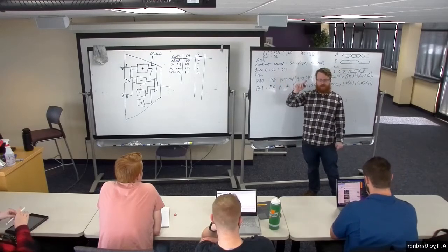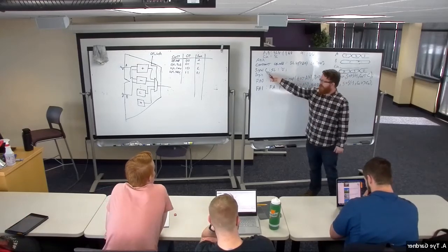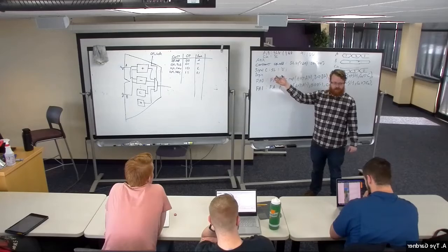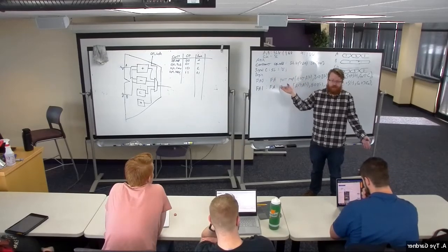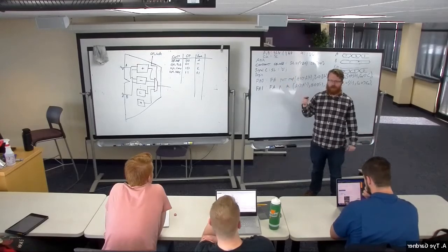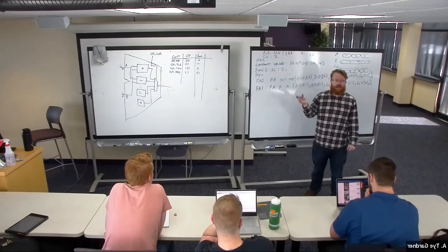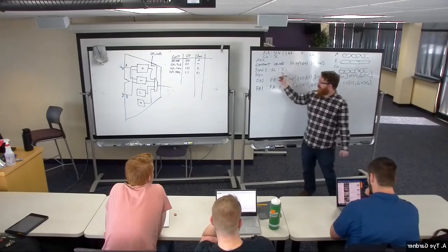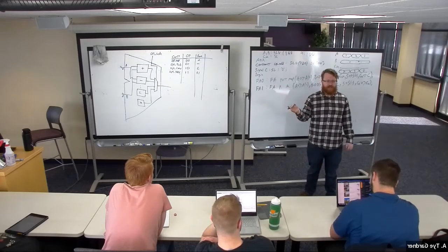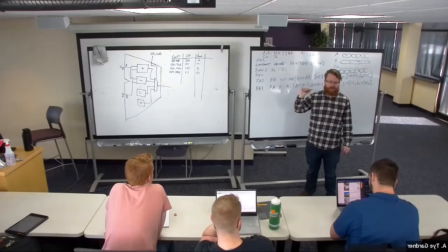Well, the issue is twofold. One, in your simulation, if signal C is not getting assigned to something, we would like it to be undefined because we didn't connect it right. But because I've declared this, it will be 0. And I'll think, oh, why is it stuck at 0? Well, because nothing else told it to change. The other issue is that when we take this code and we put it onto an FPGA, this doesn't come with it on a signal.